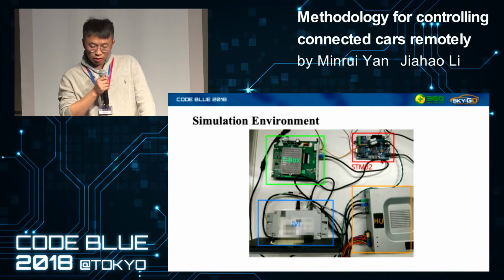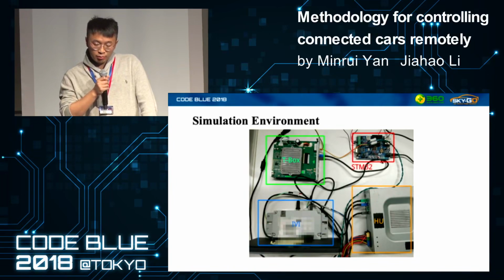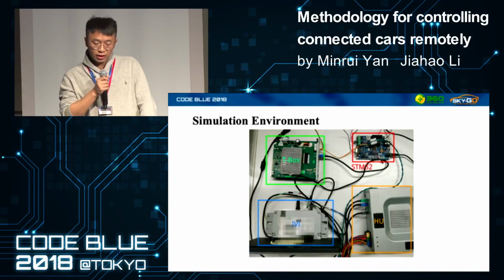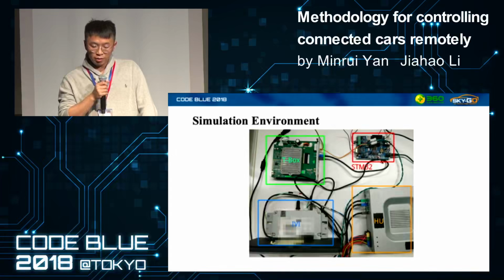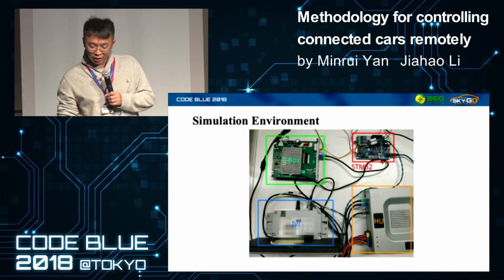Connect the ECUs according to the real car. Supply the DC power, then you need to keep sending the enable signal that you found from the real car. In this figure, we used an STM32 to send the CAN bus message to the T-box. This is a wake up command in a CAN bus message. This is a very simple case. In other, more complicated cases, more ECUs are required.